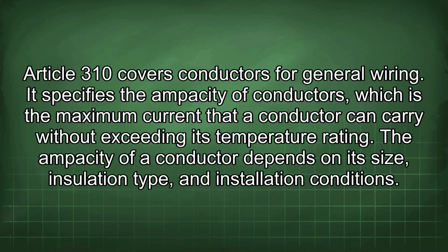Article 310 covers conductors for general wiring. It specifies the ampacity of conductors, which is the maximum current that a conductor can carry without exceeding its temperature rating. The ampacity of a conductor depends on its size, insulation type, and installation conditions.